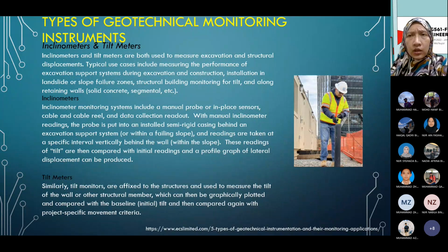Or you can also use the inclinometer for predictions by having the data on site. I mean, if you are calculating the future settlement in the next 5 years on or below the building area, you can use the inclinometers to give you the displacement of the soil for short-term and long-term stability.